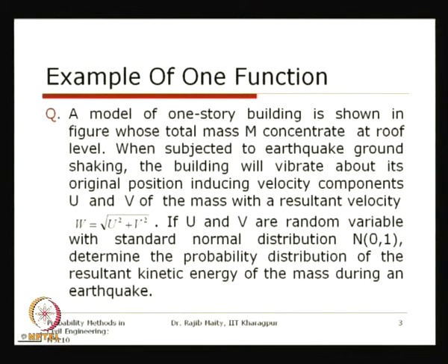So based on that, we will take a simplified one-storied structure. The general way of analyzing earthquake force is that we assume a concentrated mass at the floor level, and based on that we obtain some force at that level and calculate the kinetic energy. So here we will take one such problem for an idealized one-story structure.